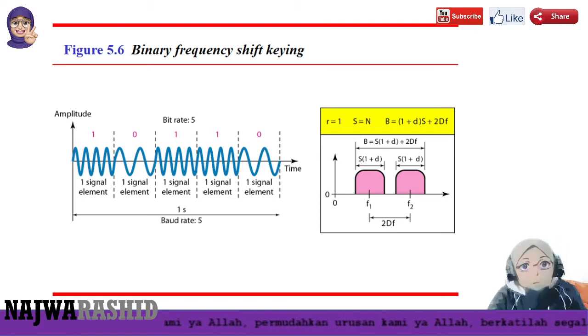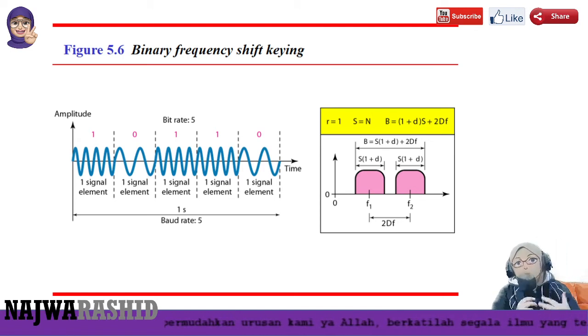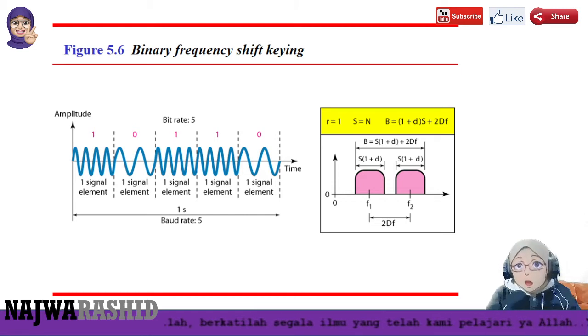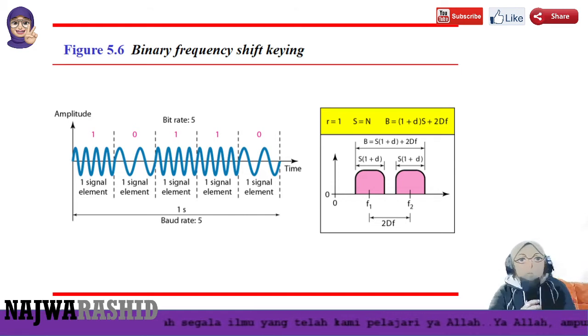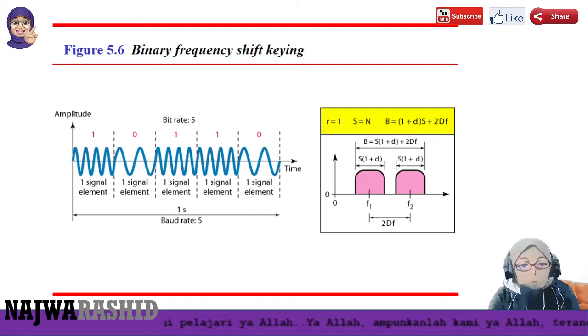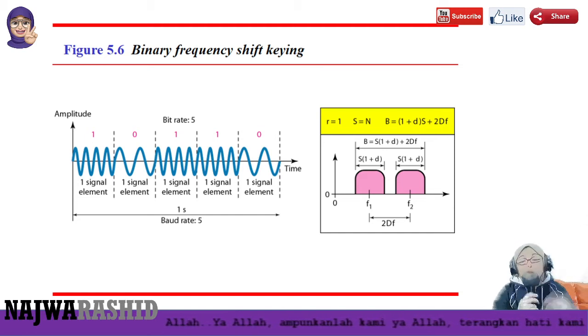Okay, the next part we go for binary frequency shift keying, or frequency shift keying. So binary equals two data values, we have 0 and 1. So in frequency shift keying, we modulate, we change the frequency.